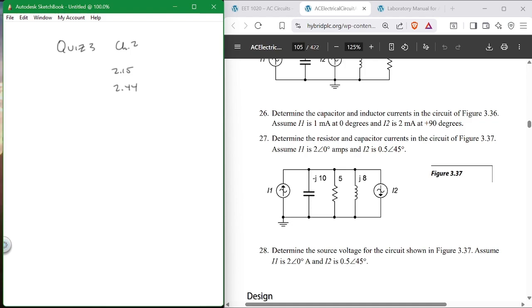And with a little time delay at the end, you don't go to the end of stroke, you go to a little point before that where you set a limit switch. So you go a little less than the full stroke, and you come back to a little less than the full stroke. So again, you put a limit switch at each end. You have to do a little soldering. It's a little bit of a lot of stuff.